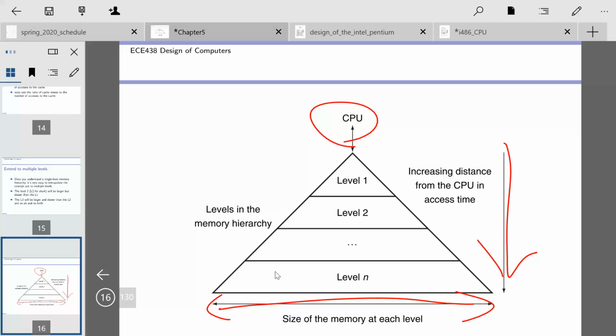3D technology is where we stack the dies on top of each other, and 2.5D is where it's kind of the half D is saying, hey, it's an intermediate step between 2D, which is where we've been at for years, and 3D, where you're stacking dies, where we have an interposer board, and we put the dies next to each other, and then we package those dies over the interposer board.